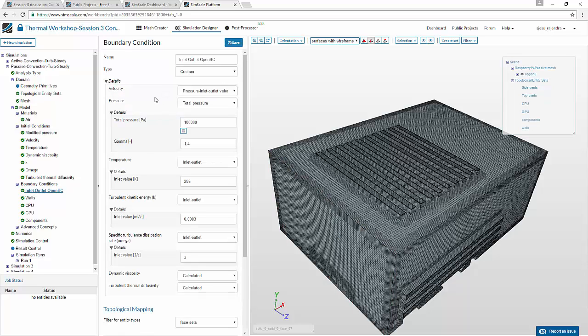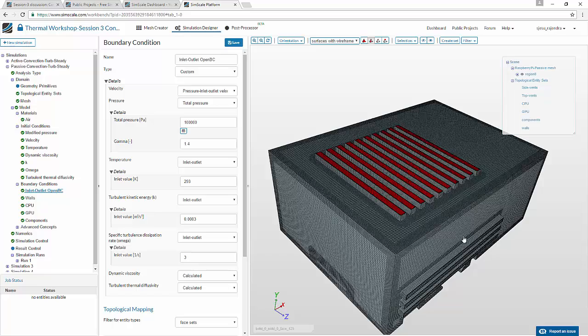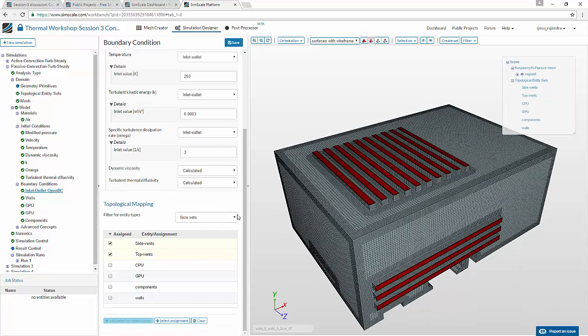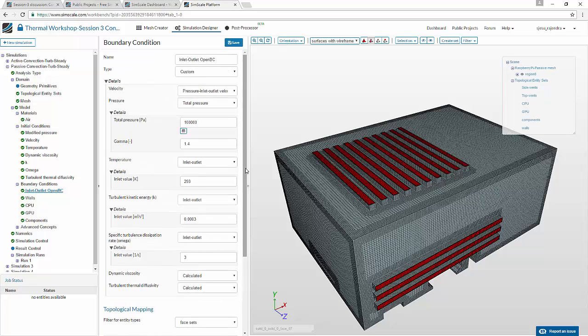And now we define something called the inlet outlet boundary condition. Inlet outlet boundary condition is something like, for these walls basically, we say air could go in and out of the same wall, but when it goes in it is at a particular temperature, and when it comes out it is at the temperature after calculation with regard to the heat source and so on.